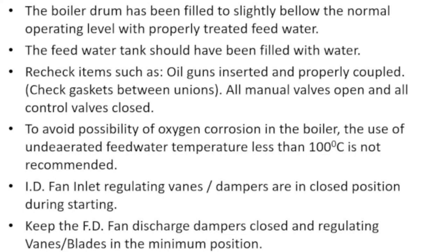Recheck items such as oil guns inserted and properly coupled. Check the gasket between the unions, all manual valves open and all control valves closed. Now to avoid the possibility of oxygen corrosion in the boiler, the use of undeaerated feed water with temperature less than 100 degrees centigrade is not recommended. Now ID fan inlet regulating vanes or dampers, they are in closed position during starting. Keep the FD fan discharge damper closed and regulating vanes blades in the minimum position.